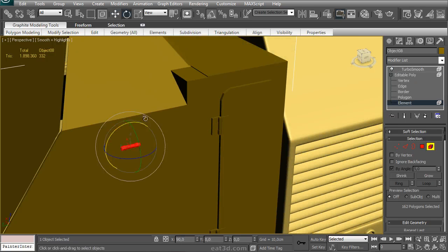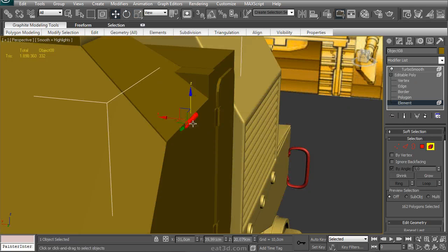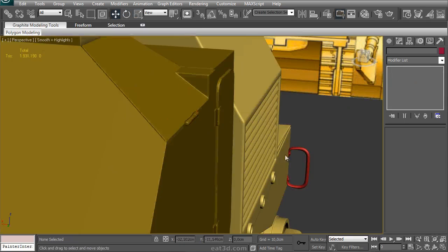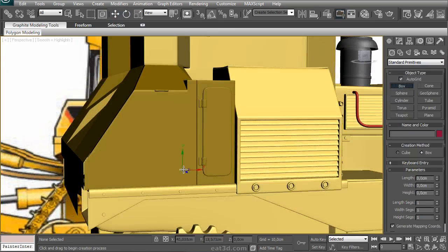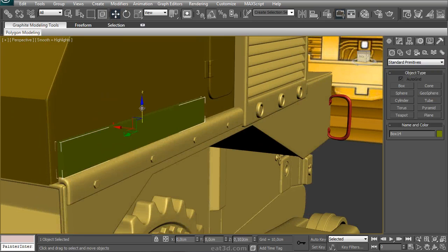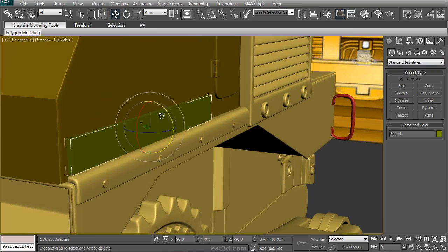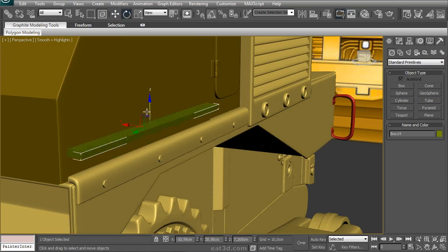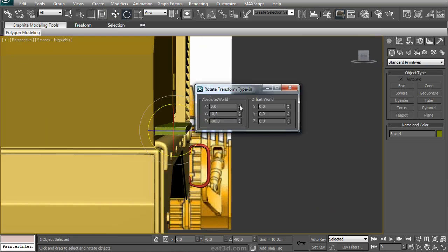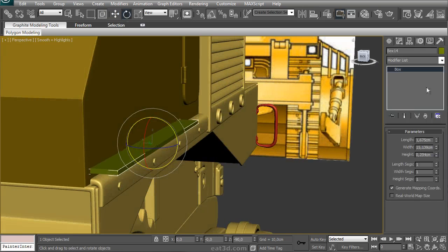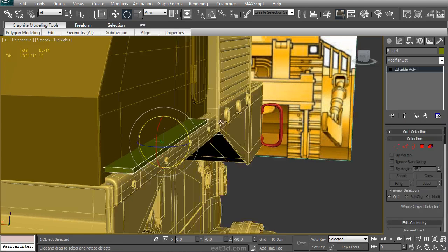And I'm taking this same little detail and I'm going to use it somewhere else. Why? Because that shape seemed to look like it was the same shape. Scaling it around, moving it a bit. It's always easy if you can reuse detail, saves work. Now here's an interesting one. This one isn't just a simple box. It's a box with some triangle shapes that are attaching it to that main part. So I'm using a box as the base.